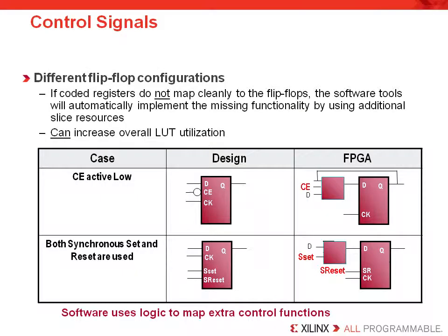As I mentioned earlier, your synthesis tool can map clock enable and synchronous set or reset functionality to a LUT input. This is very powerful for being able to group registers into the same slice since all the flip-flops are required to share the same control signal. In this example, we see how a clock enable and a synchronous set or reset is mapped to a LUT input. Now this is very helpful, but a job only your synthesis tool can do.